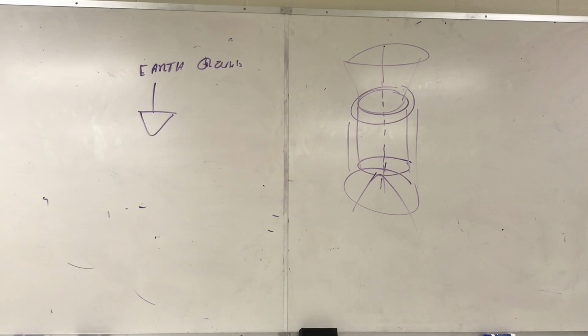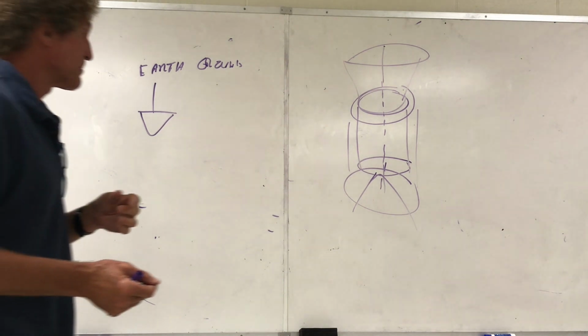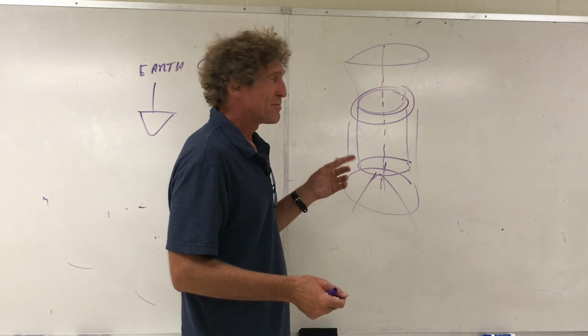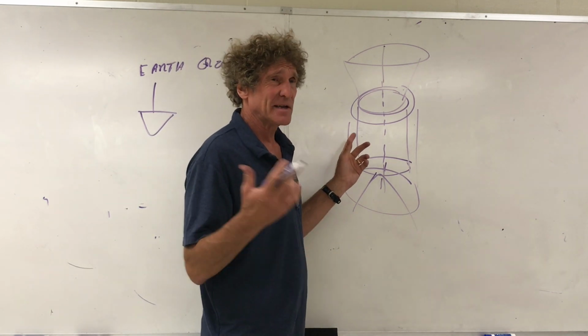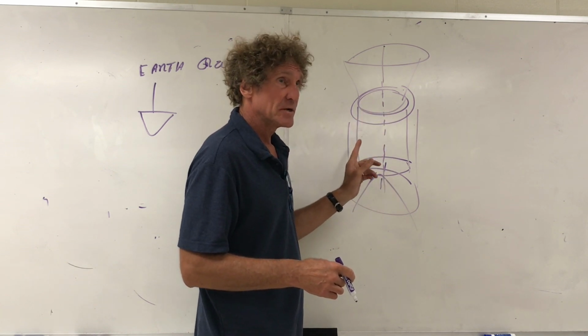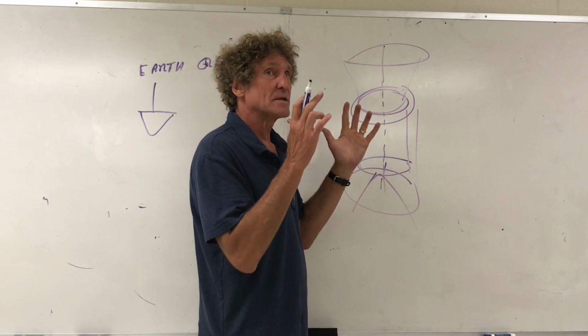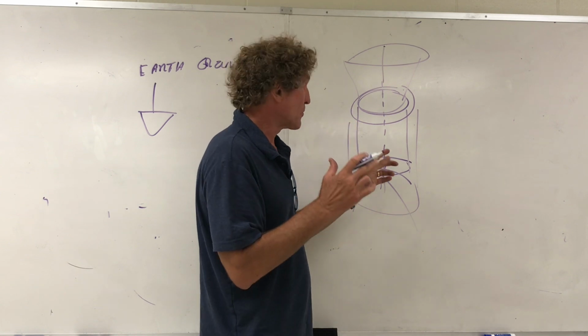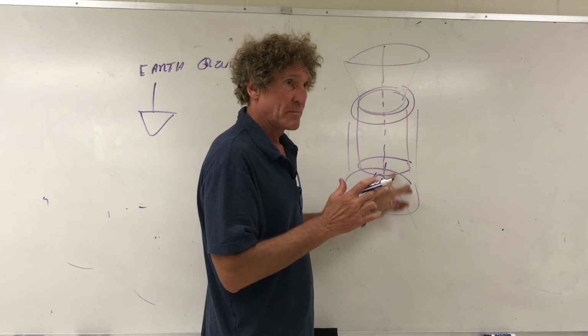You know how fuses are rated like 10 amps and all this stuff? There's a certain amount of time before they blow at 10 amps. Anyway, this thing was going to blow, I don't remember what it was, it went over like 10 amps or something, we calculated this. But we fill it with sand. The reason we do, as soon as this wire blows, we want the sand to collapse on it so there won't be an actual arc between the 2 points.